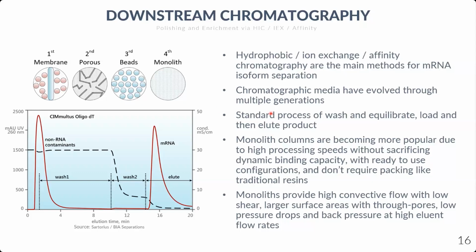So chromatographic operations do take some amount of time. The unit operation time is on the order of hours, and as you get more and more upstream product, the fact that you have to equilibrate the column, load the column, and then elute the material of interest, all of that takes some amount of time.